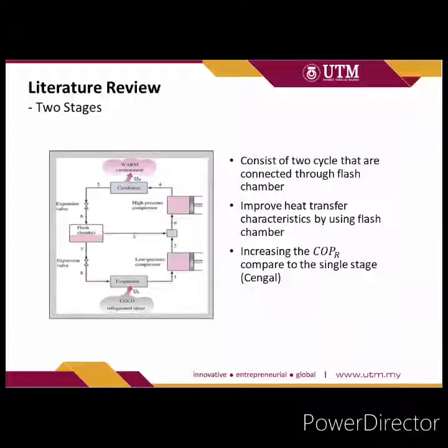Next is two stage. This system consists of 2 cycles that are connected to a flat chamber. It improves heat transfer characteristics by using the flat chamber. It also increases the COP compared to the single stage.